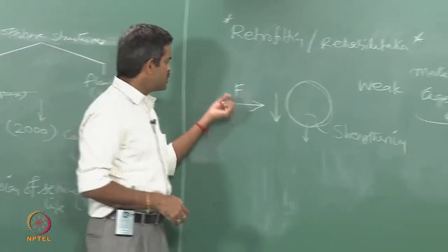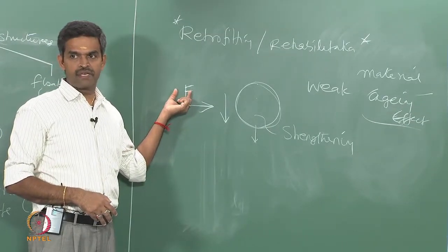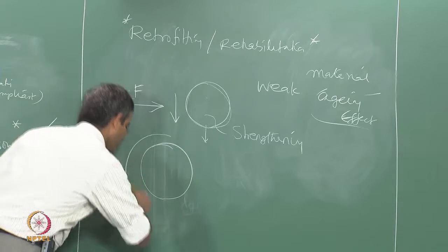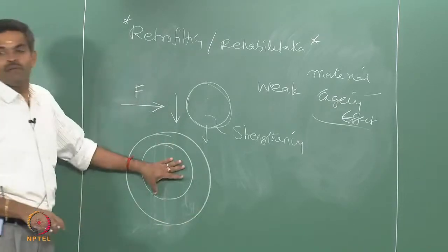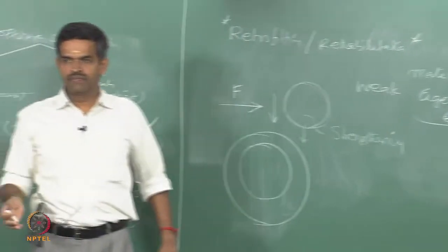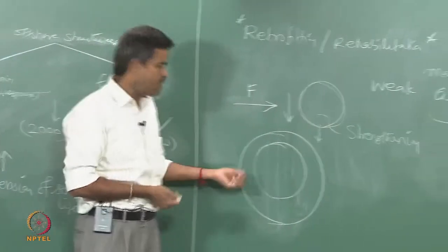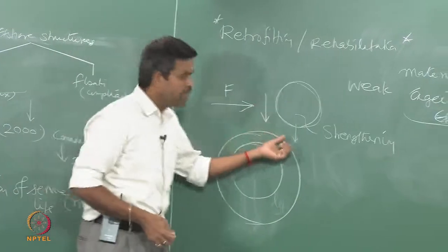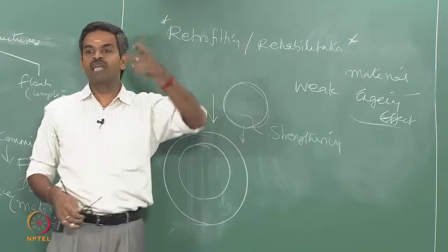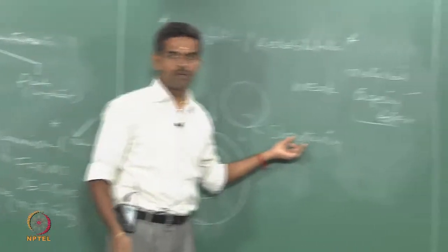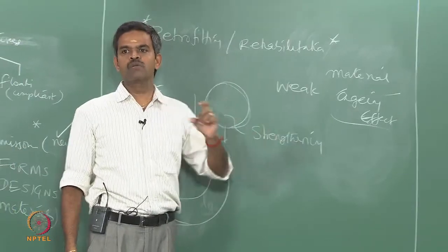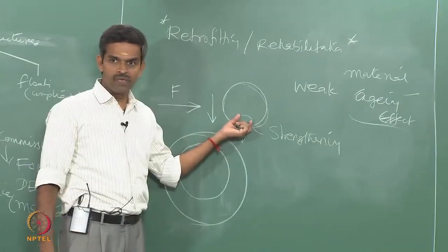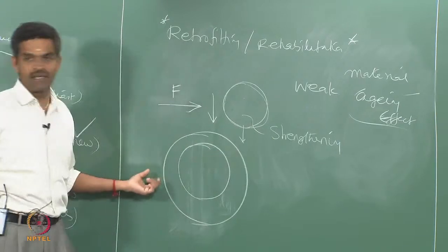Now the best part is this environmental factor, you cannot reduce the force actually by any technique. So what they do is, they have a member, you put a cover over the member and protect the member and sacrifice the cover and keep on changing the cover, because the cover is not to be put for the entire length or the entire depth of the member, because the member is not uniformly damaged for the entire height of the member, only partial damages are happening. Even if you look at the strengthening part, people do not strengthen the entire member, they only strengthen possibly the joints or the connections, only a few points they will strengthen. So those points which are weak from a strength point of view, only protect them.